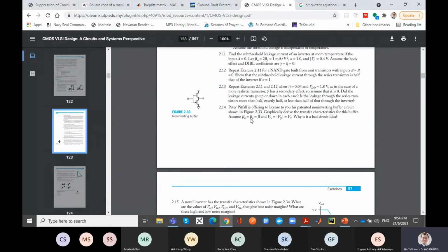Okay, I'll give you a bit of a hint for 2.14. In this case, VGS is here. This is going to go to logic 1, so this is going to be transmitting. So you're going to pull this up, going from logic 0 to logic 1. When it's logic 0 here, this is logic 1. So VGS is very large, right? So there's a large, nice, happy channel here.